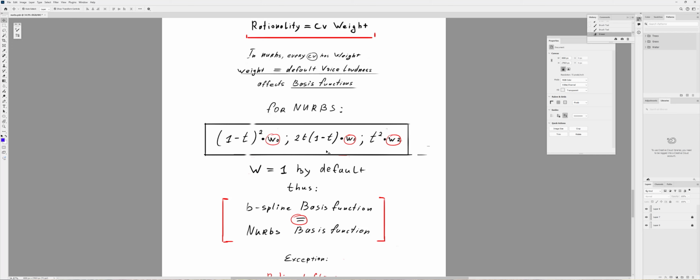Now, of course, Alias and other CAD systems need to know the algorithm, and the algorithm is based on very specific math, and it works only when specifically designed to operate with conics. Conics means the revolves, profiles, and circles, right? So if you create a circle, or create a revolve in Alias or in ICEM, for example, then you may go into the settings and say, I want my NURBS to be real NURBS.